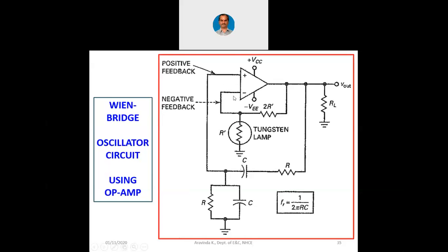We have seen earlier that negative feedback has 6 advantages. That was in the case of amplifiers, but now this is an oscillator. Still, those advantages of negative feedback are to some extent obtained even in this circuit. It has both feedbacks. Anyhow, it has to be a negative feedback, right? Because the amplifier has to produce 180 degree phase shift here. An operational amplifier used in the inverting configuration is negative feedback itself. So it is necessary here.